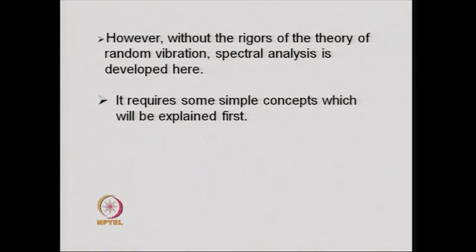Then comes the coherence function. Whenever we have two random processes, for example, if we have a displacement of a structure x1(t) at, say, the top of a frame and x3(t) at the first floor level, between these two random processes there will be a lack of correlation, or there is a phase gap or a time lag.